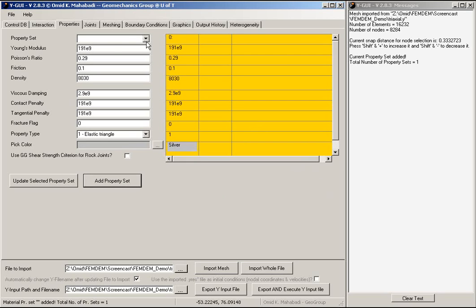Then I will put in the values for the rock specimen. Let's say that the average rock, which consists of 90% of the rock specimen, these are just assumptions I'm making on the go, has an elastic modulus, or Young's modulus, of 53 GPa, a Poisson's ratio of 0.23, a friction coefficient of 1.27. Remember that this friction coefficient is the tangent of the friction angle, and 2650 will be a good density.